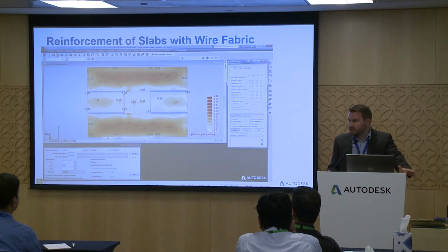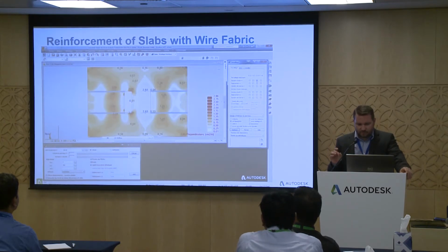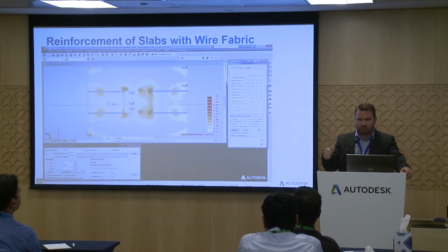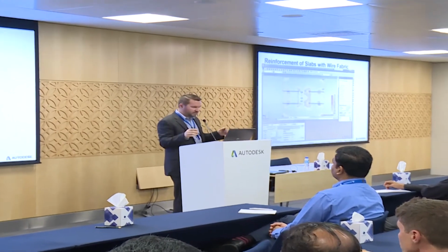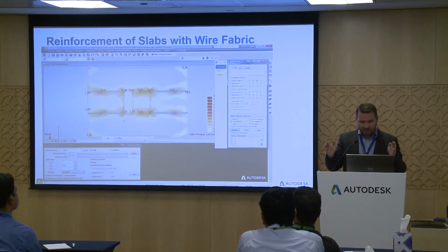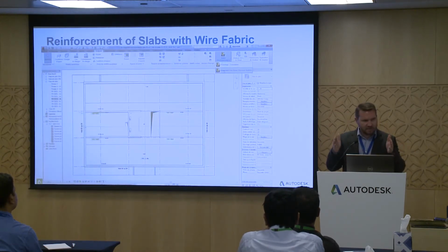And once you have this, you can come back to the element. The thing is, you will send the analytical element, and when you put reinforcement, you will put reinforcement on the real slab, so you can have some centimeters of difference, because, if you remember last year I explained to you, to calculate this building, you will have to simplify the element to align on reference planes, on axes, and so you can get small differences. But the main idea is here, and it's very useful.